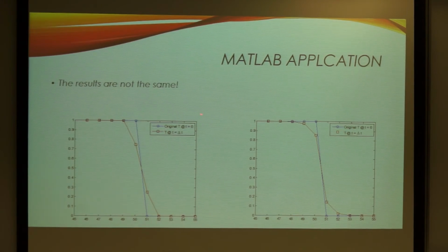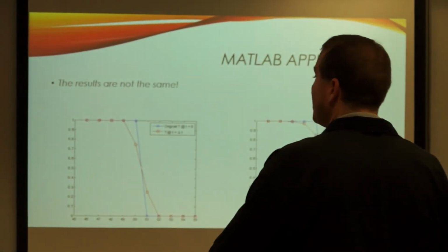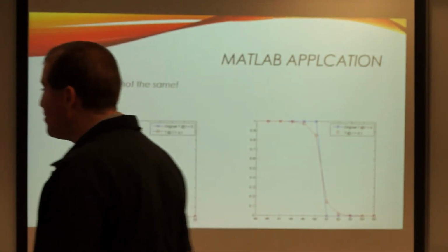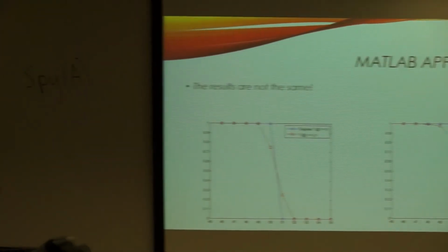So on the left-hand side was last week's answer. Explicit FTCS. Using the same dt, 0.25 by 10 to the negative 4. That's the result from last week. The right-hand side is this week. That's implicit. Same dt. But the solution's different. And the reason is because with our implicit solver, we can compute all of the dt's at the same time, so we're able to get a better answer. In the FTCS, we can only update the value at any 2 points.